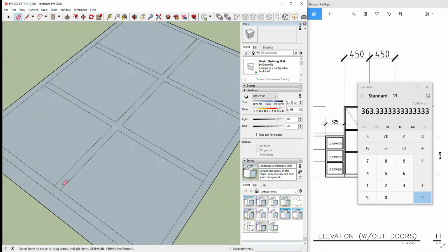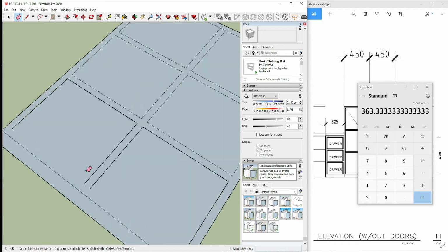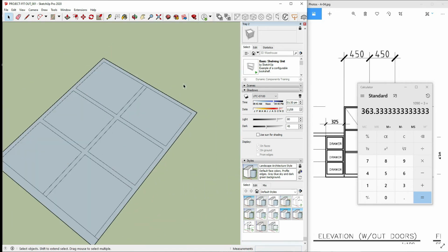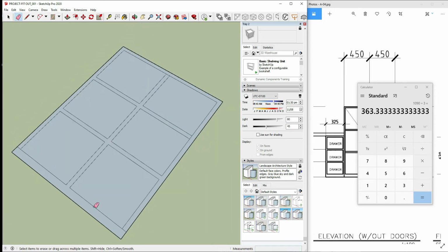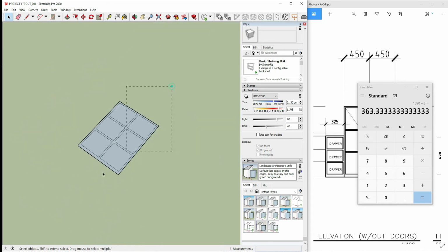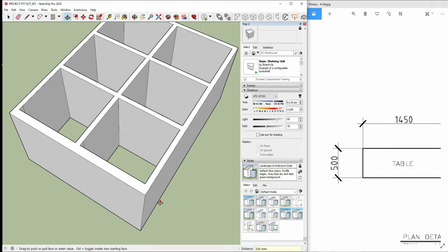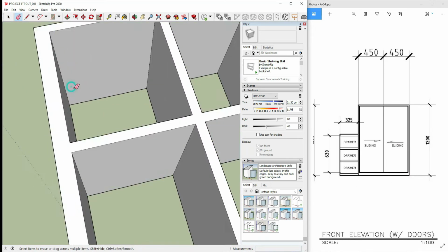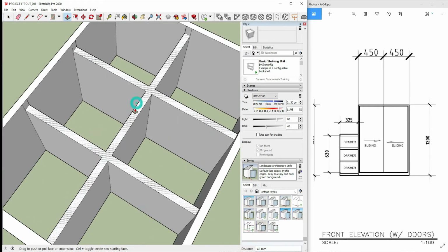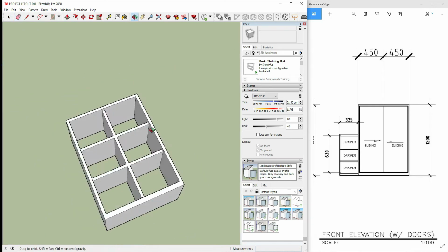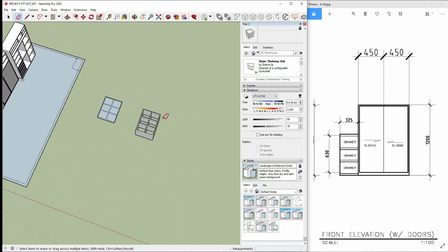Then, I delete unnecessary lines and objects to proceed with the Push-Pull tool. I make an additional copy of the object to create a spare that we can use later in creating doors or drawers of the cabinet. Now, we use the Push-Pull tool to create the 3D model. Adjust the wall divider by making a line on each side for the space of the sliding door. I delete unuseful lines and create the object as a group for easy editing and adjustment.